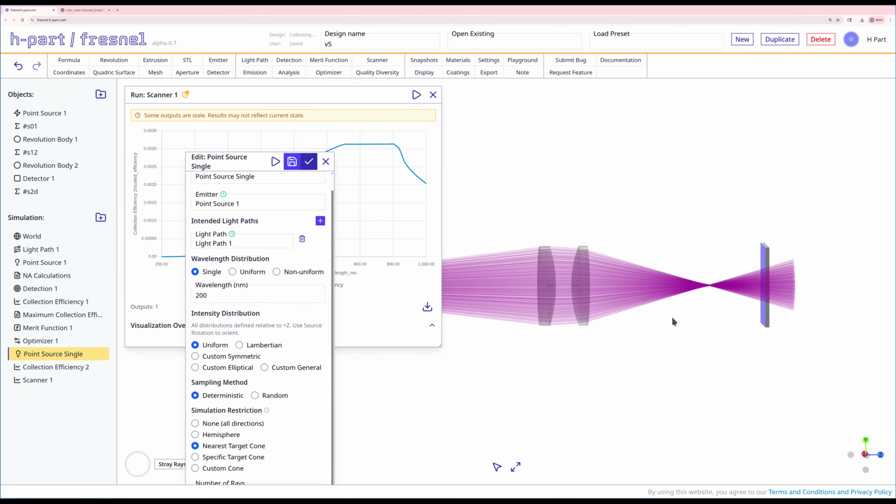Save it, recast it. You see a pretty dramatic shift in the focal length. Well, now all that ultraviolet light is focusing many millimeters ahead of our fiber, and very, very little is actually making it in. Now in LIBS and some very bright applications, you might actually be able to get away with this. But here we're going to assume that you cannot.